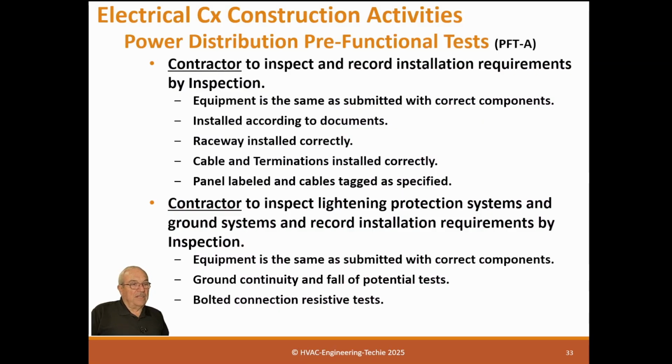There are different kinds of ground rods. If the soil has such poor conductivity that a single ground rod won't work, then they'll put down a mat of number 4 wire or bigger, maybe aught wire, and that's a ground mat, and that might work. Or if worse comes to worst, you can use a salt ground rod.